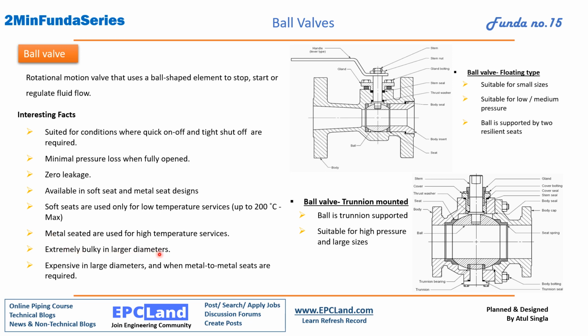Extremely bulky in larger diameters. The size is very high if we go for higher sizes because the ball size increases with the diameter. Expensive in large diameter and when metal to metal seats are required. So as we go for higher sizes and go for metal seated, that means for higher temperature, it becomes a little bit expensive.